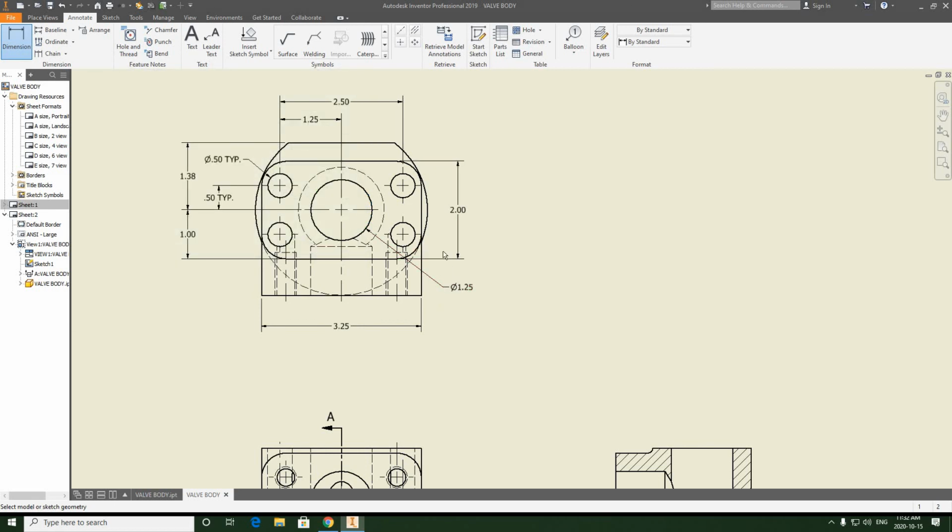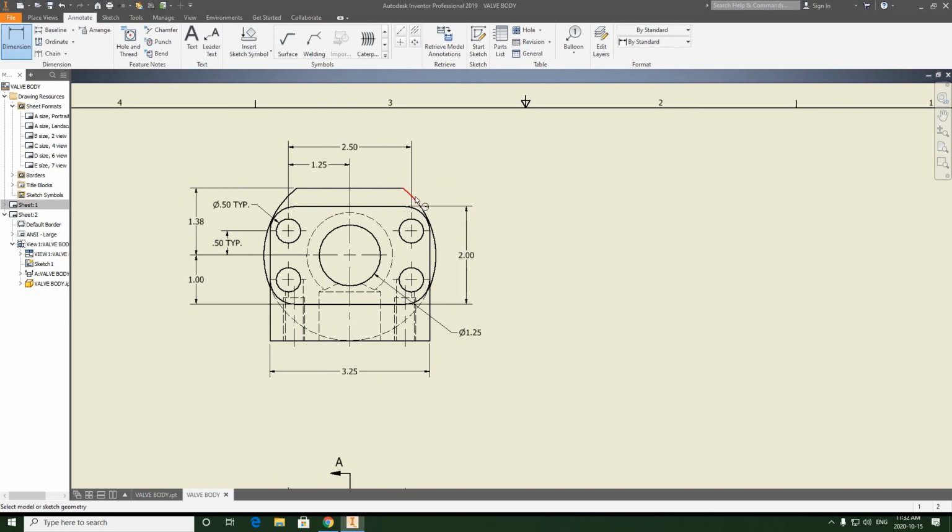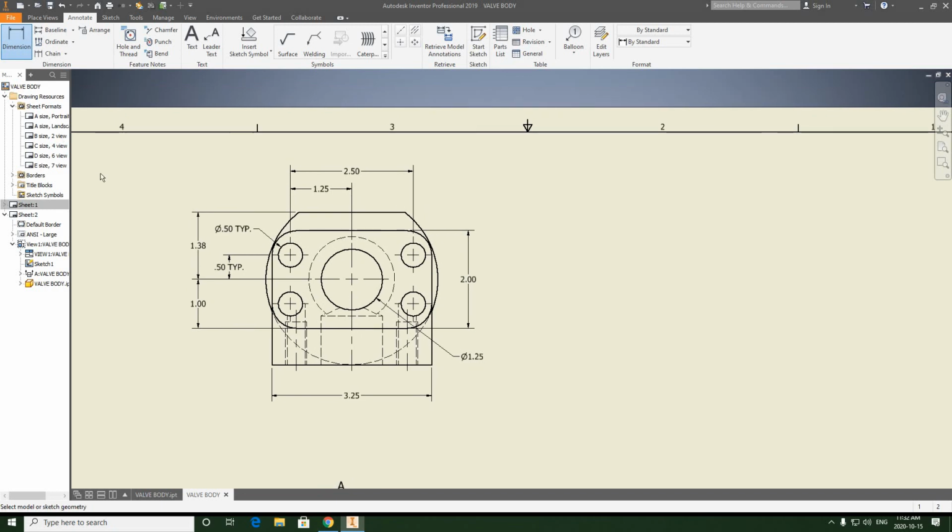I need to keep this one low because I have a couple of dimensions I'm going to have to place up here, and one of which is the radius of the base. I'm going to attach that dimension here, and I'm going to place it about in line. The R is in line with about the 2. Right? Keeping a similar distance to what we see at the bottom. Click OK. All right. That's about all we can do with the top view for now.